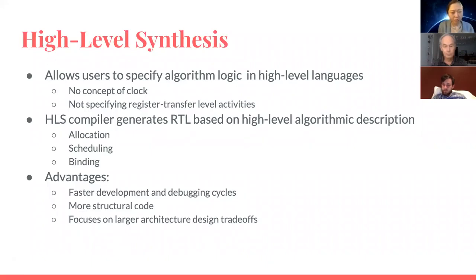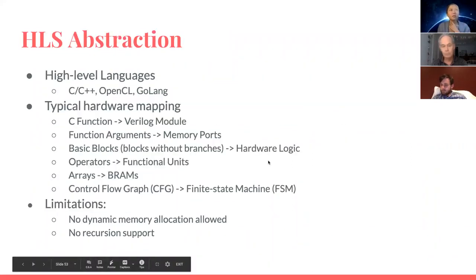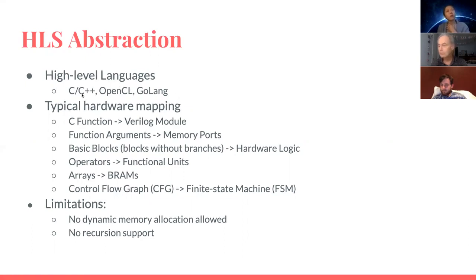So the decisions made by binding may imply sharing functional units between operations and sharing registers and memories between variables in a high-level language like C. And then, here are the different high-level languages currently supported for high-level synthesis.